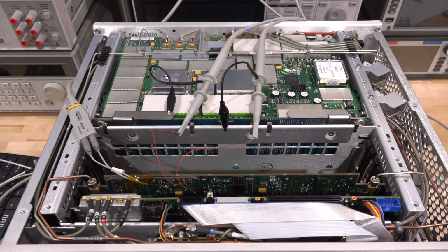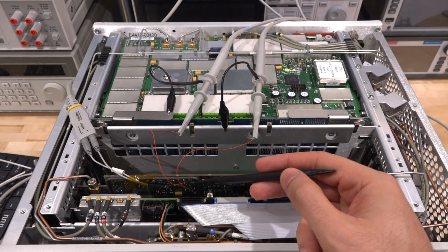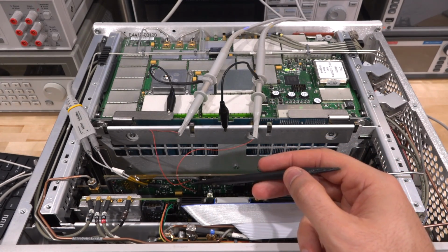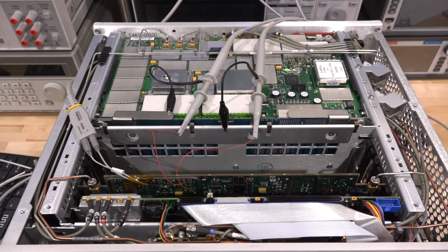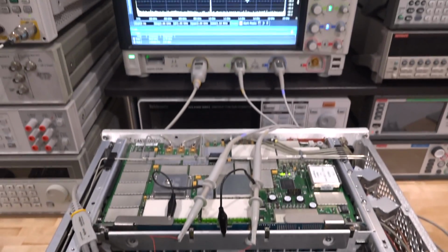So after everything that I described, I went ahead and I connected two wires directly to the opposite sides of the diodes, the varactors in the VCO. So we're basically looking at the coarse tune and the fine tune at the same time. I also have the active probe connected directly to the output of the VCO as well, so we can look and see what the oscilloscope says.